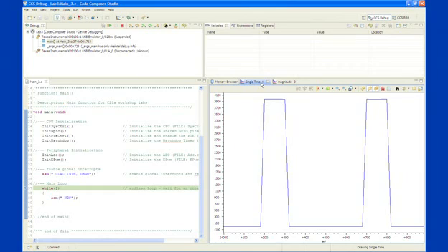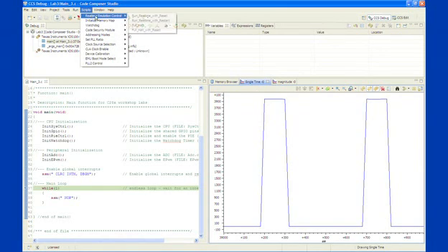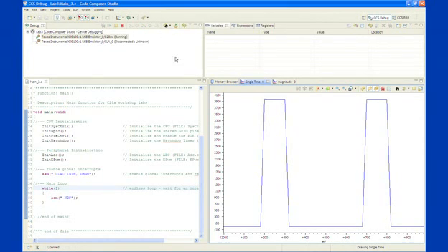And what I'm going to do this time is run the code, but we're going to run it in real-time mode. And by doing that, you'd click on Scripts, Real-Time Emulation Control, Run Real-Time with Reset. And right now we're running in real-time mode, and if you notice right down here, the values are changing. And what I'm going to do is very carefully pull the wire out of the ADC and watch how the graph changes.